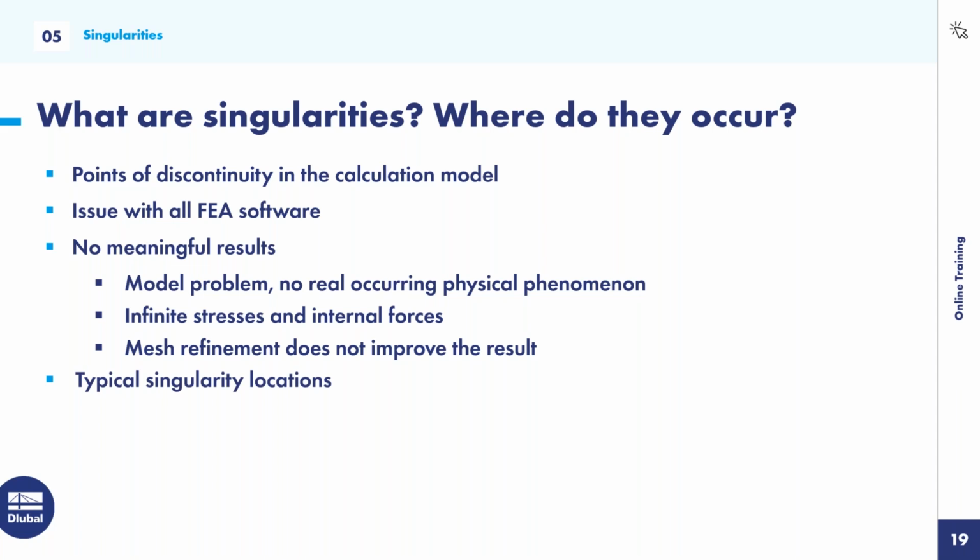There's no real physical issue with the structure. It's just how the software is solving the model. So this causes infinite stresses and internal forces at a singularity. So you'll see very high stresses, very high internal forces at that singularity.